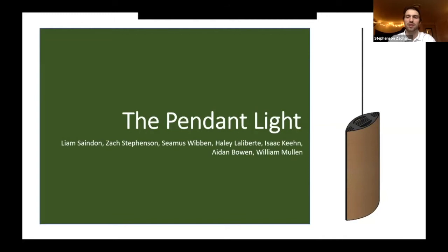One question: how was the excess end material removed without splitting the veneer? Yeah, I went over that pretty briefly on the fine handwork slide, but we pretty much used a razor blade and just really carefully scored the veneer over and over and over again until it came off pretty seamlessly.